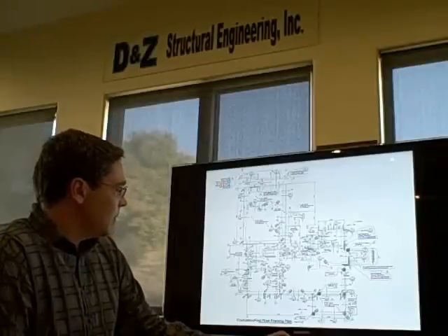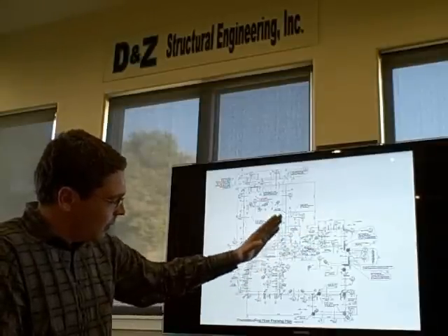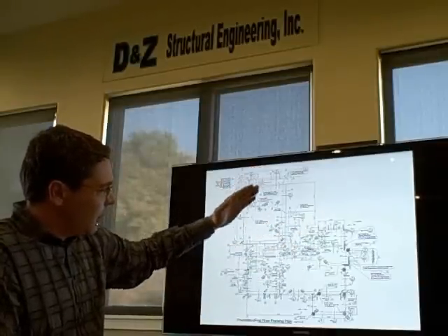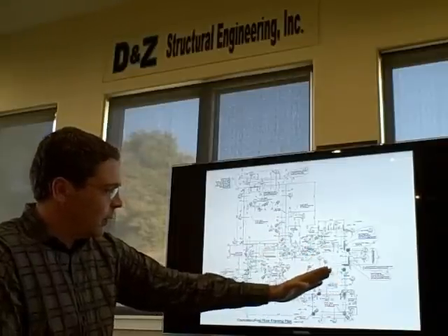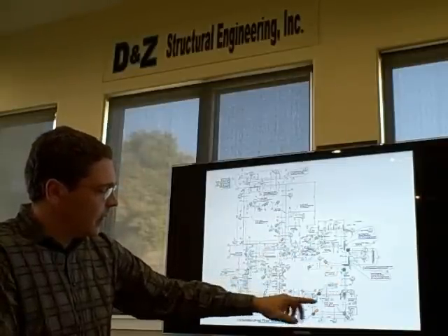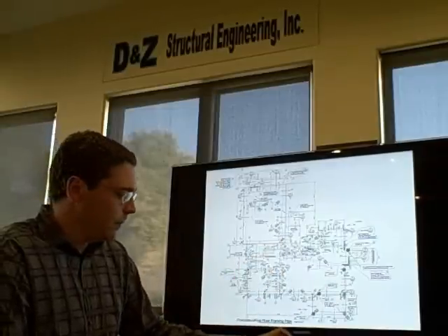Again, another house where the cut fill line would be about right here, so competent soils would be up on this upper half of the structure, and then down here would be more fill, unstable, and if you didn't use caissons, very likely you'd get settlement in this area and cracking of a standard foundation.